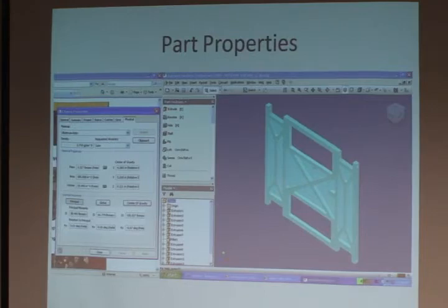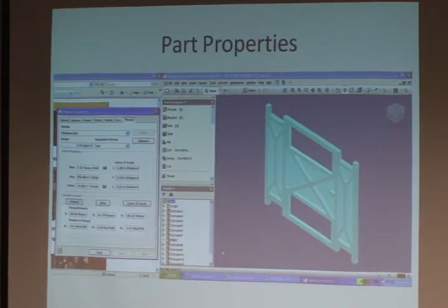But remember to take into account that you're probably not going to have your battery in here. If you're going to buy it off a website already made, they'll probably tell you how much it weighs. Look at how much your motors weigh. Wiring is heavy. You might not think that, but it is. Nuts and bolts, they add up very fast. Don't design your robot in the computer to weigh exactly 15 pounds. Give yourself some room. You don't build it to 12 pounds, because when you put that wiring in, that's going to take 3 pounds quickly.